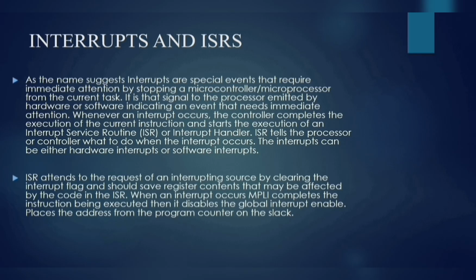Now coming to the interrupt. Interrupts are special signals that temporarily halt the normal execution of a program to handle an urgent task. It can do the work and then return to the program, which is very crucial and important. It is a signal to the processor, generated by hardware or software, indicating that something needs immediate attention. Whenever an interrupt occurs, the microcontroller completes the execution of the current instruction.